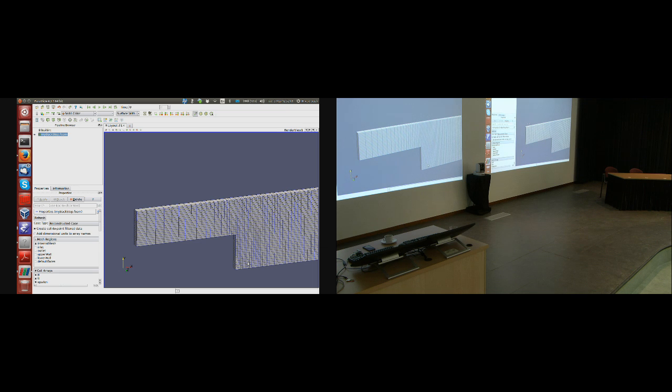So the cell aspect ratio of that cell is within, I don't know, 20 to 1, right? If I make my geometry this wide, it would be 1,000,000 to 1, and I'm going to have a round off error in the calculation of the volume. So there is no guidance really of how thick it needs to be. Just make it look pretty. Okay? What do we do next?